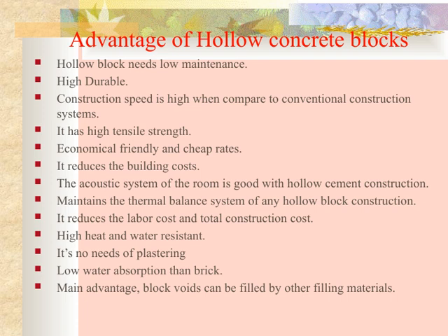One great advantage is that they don't require plastering, which further cuts down on finishing costs and time. They have low water absorption compared to bricks, making them more durable and less prone to damage from moisture. Finally, a very versatile feature is that the voids within the blocks can be filled with other materials, allowing for customization based on specific structural or insulation needs. Overall, hollow concrete blocks are a smart, cost-effective, and durable choice for modern construction.